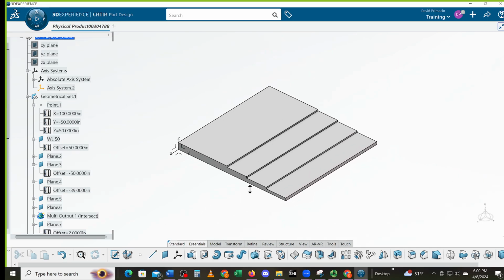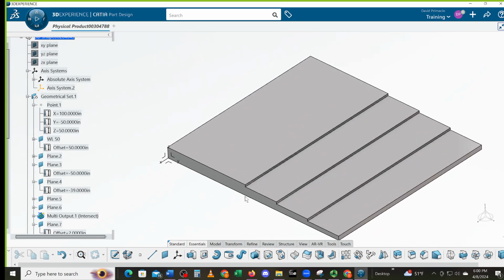All right, so that was my goal, to get you guys orientated with the planes and how I did it. So apparently, don't use the trim. Just split everything. Because when I trim, it trims the lines, but it makes the two lines you keep one entity instead of separate lines like we had here.